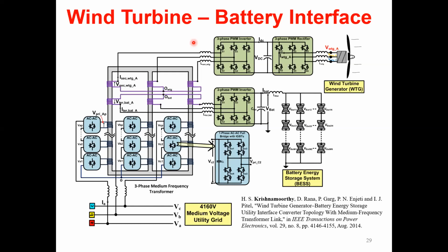So you may need more series stacked AC converters. So that's this topology. Like I said, once we understand the basics of the solid state transformer, all these concepts are very straightforward, considering it's just one AC converter on one side. Depending on whether you have an AC or DC, you use an inverter or again an AC converter, and then you just combine it with the transformer.